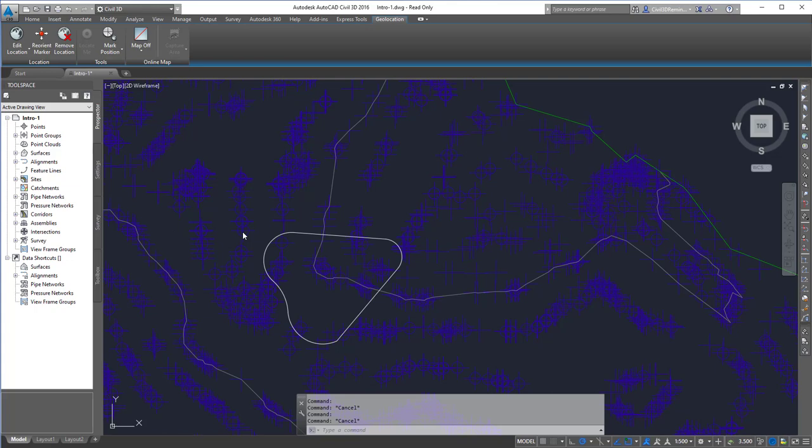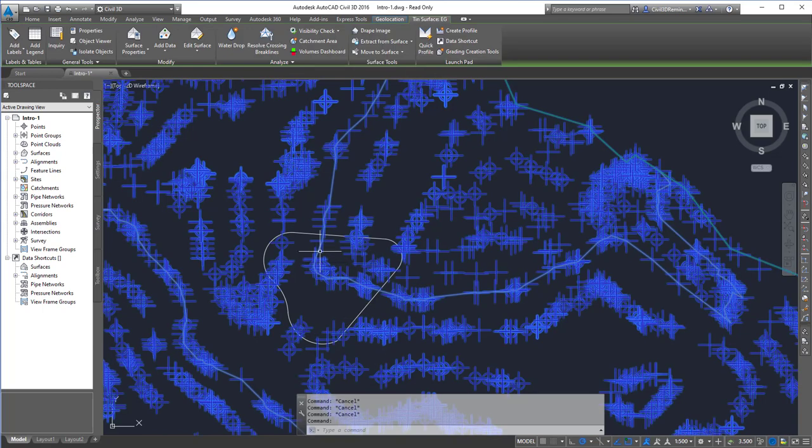This video shows various ways we can modify a surface's elevations within an area. The first way I'm going to do it is by lowering the individual points within a surface. In order to do this, you need to have the surface style have the points showing.